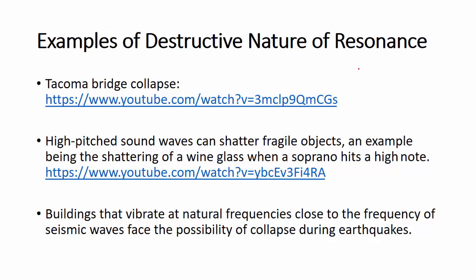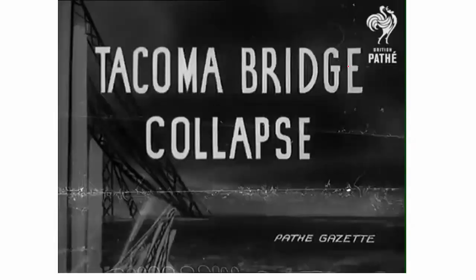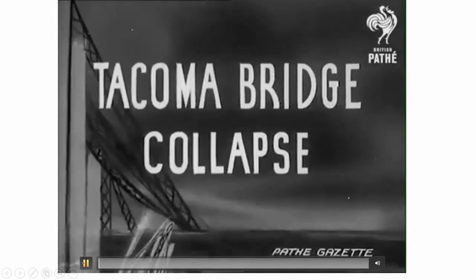So some buildings that are close to the epicenter of the earthquake do not suffer much damage compared to buildings that are further away from the epicenter, because the wave that propagates from the epicenter happens to match the natural frequency of the buildings that are further away, and can cause more damage. Let's look at a situation in the 40s, where a bridge was constructed in the US called the Tacoma Narrows Bridge, a newly built bridge that had been open for a few months.